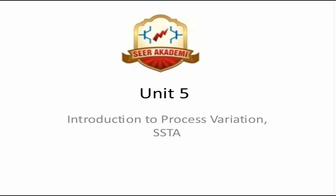Hello everyone. Welcome to what is probably the last lecture session for Unit 5. This session I will introduce the concept of statistical STA. This is where the STA methodology is moving towards SSTA, given the lot of complexities in technologies that are lower than 45 nanometers. Although we are not at a stage where we are doing 100% SSTA, we are using some of the tools or some of the methodologies that are somewhat statistical in nature.